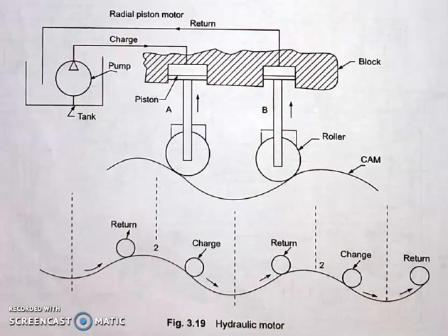After the hydraulic mechanism, next is the undercarriage unit. This unit is very similar to that of the diesel shovel undercarriage unit, having a track and carrier roller attached to the crawler frame. The only difference is the shape of the track shoe. Hardened gauges are provided at the exposed side of the shoe so that more tractive effort can be obtained during operation, instead of the flat surface of the shoe in the diesel or electric shovel.